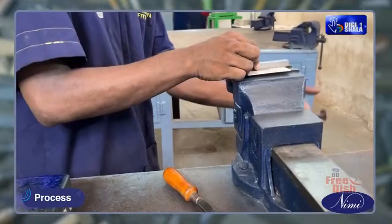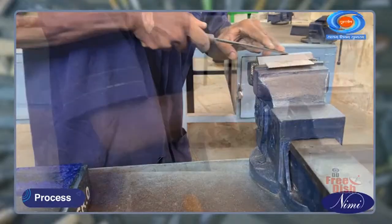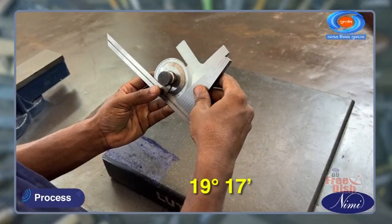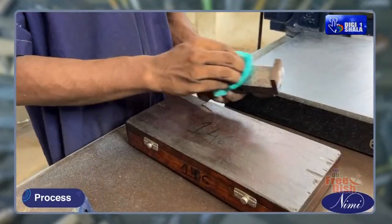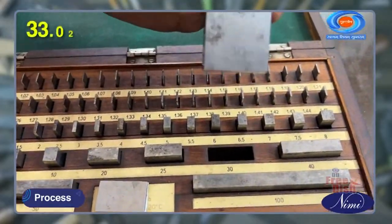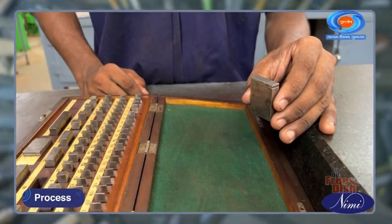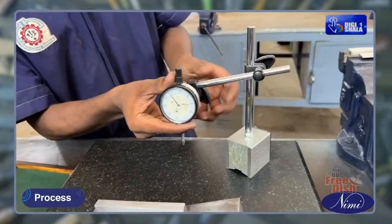Similarly, scrape part 2 and maintain the angular surface without high spots and at angle 19 degrees 17 minutes. Clean the surface plate, sine bar and slip gauge with a soft cloth. Select the slip gauge to the height of 33.04 mm. Set part 1 on the sine bar and clamp it properly. Fix the dial test indicator in the stand.